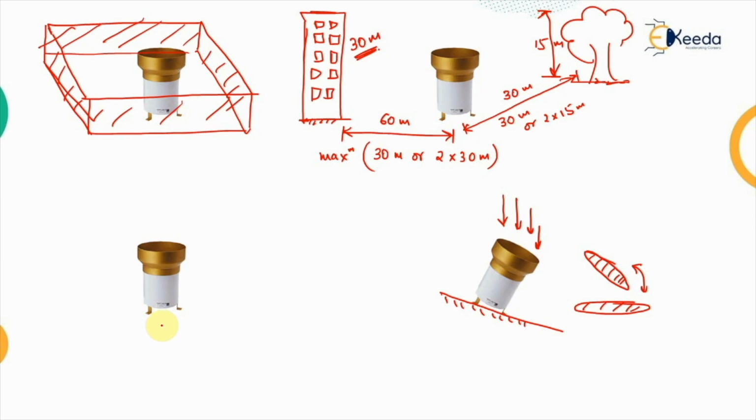And the fourth one was regarding the level of the rain gauge, that there should not be any wind effect, so it should not be that high, and it should not be so low that there are chances of flooding of this rain gauge.